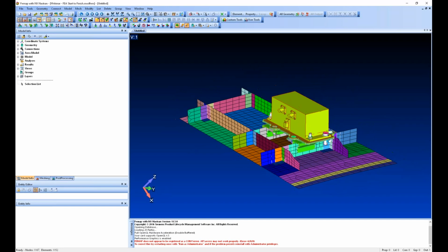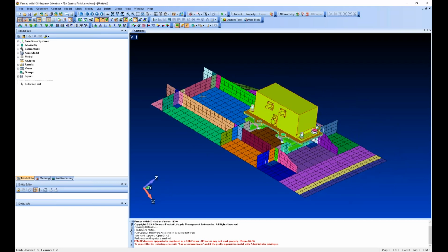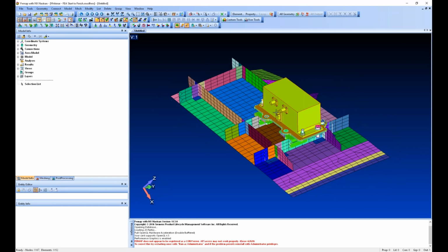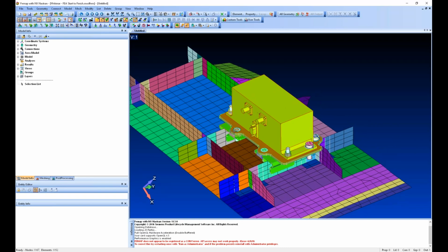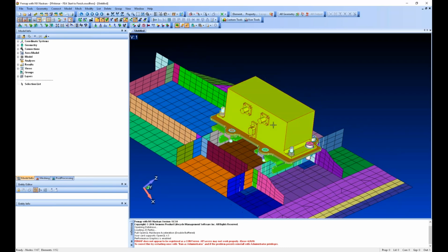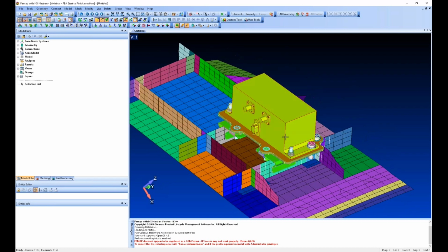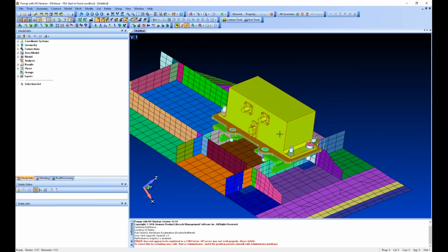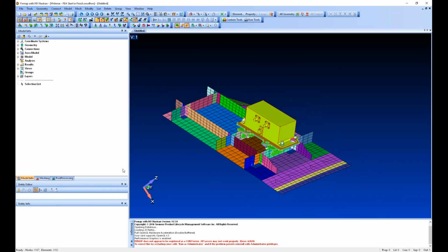Now, the reason we're deciding to use a breakout model here is because the entire FEM of the pressure vessel may be many hundreds of thousands of nodes and elements. So it's very large. And to properly analyze this subcomponent and the brackets that support it, we need to analyze a number of inertial load cases where this thing is accelerated in any number of directions in the X, Y, Z directions and combinations of positive and negative accelerations. And so that can mean a lot of load cases. So if we're applying a lot of load cases to this larger FEM, it becomes computationally expensive.